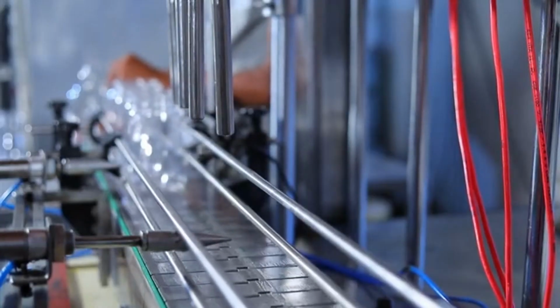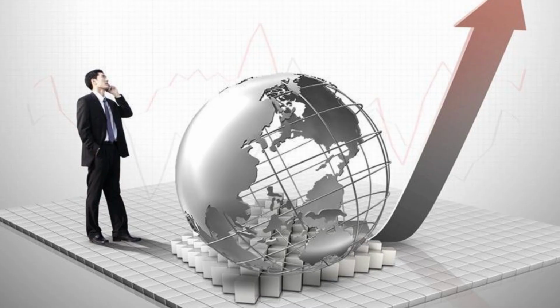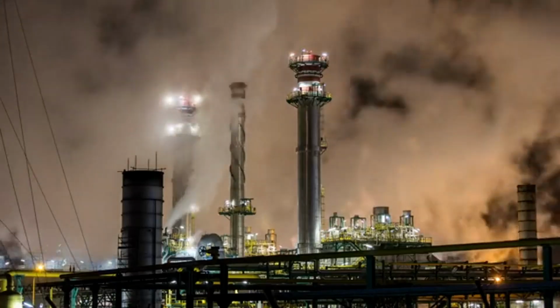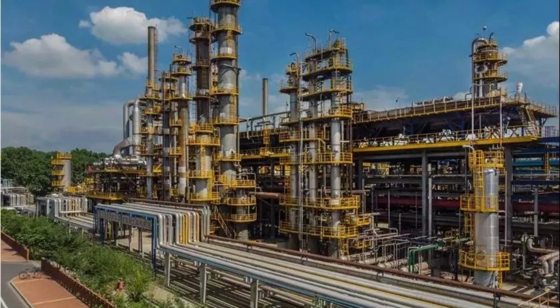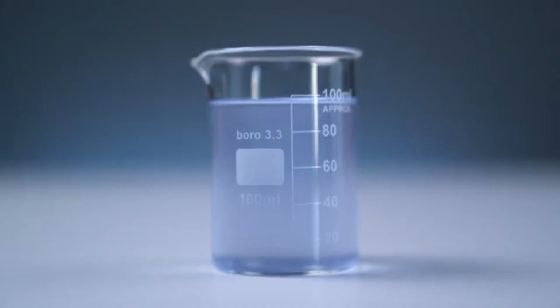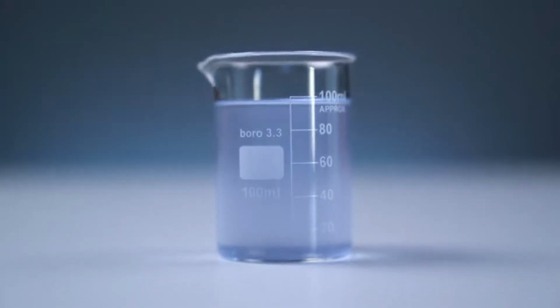Upgrading is usually a two-stage process. Coking or hydrocracking, used to break up the molecules. Coking removes the carbon, while hydrocracking adds hydrogen. Hydrotreating, used to stabilize the oil and remove impurities such as sulfur.